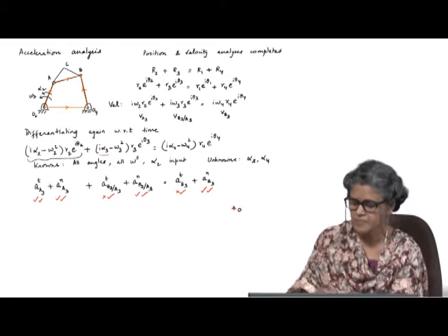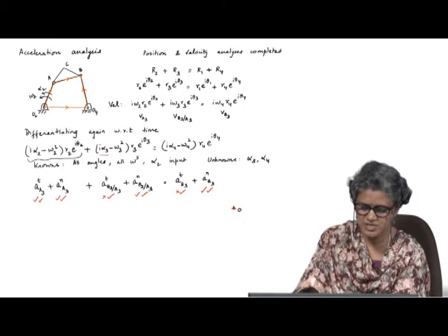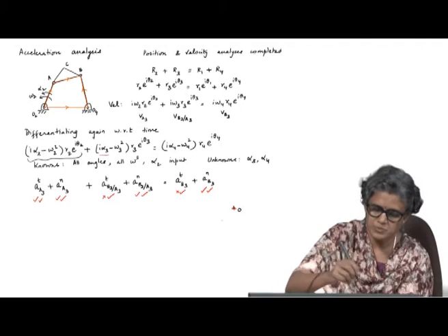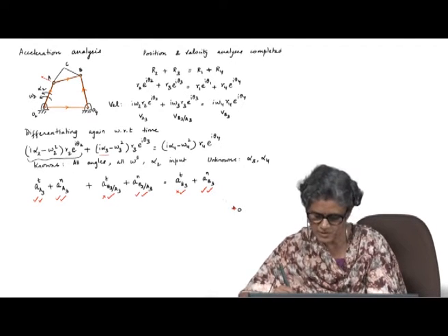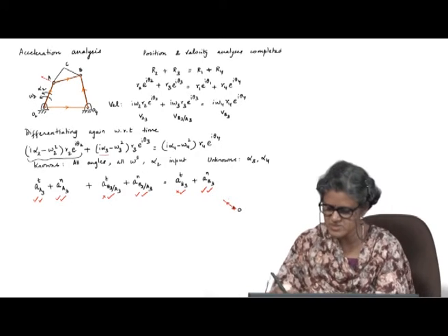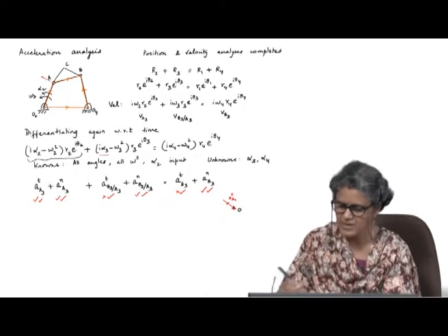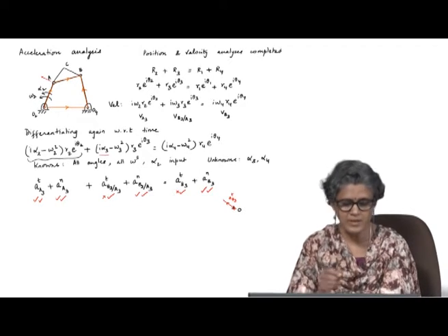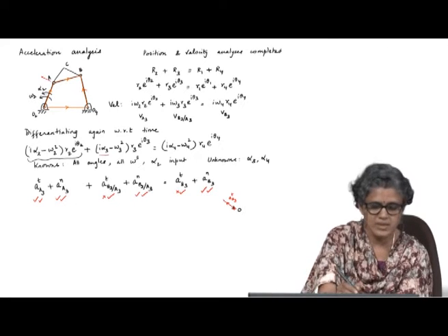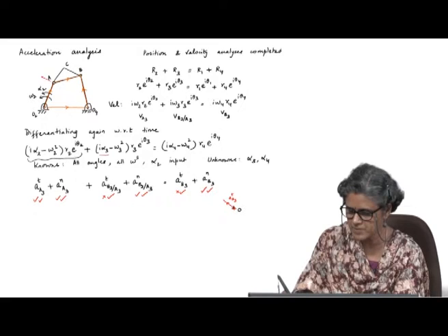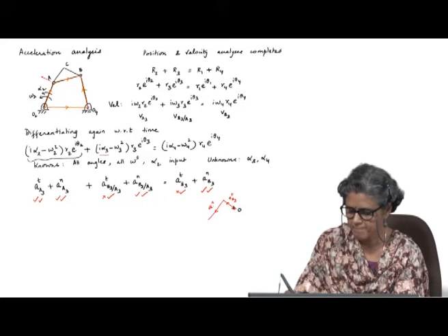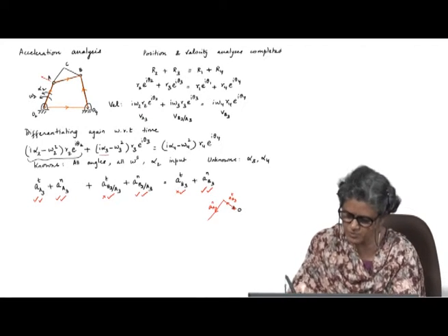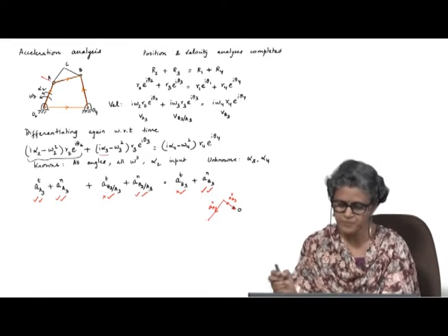So, if this is O, I know the tangential component of this, which would be like this, right, along that direction. So, this is A tangential A3, known. Okay. Normal component would be along from A to O2, that direction, that is also completely known. Okay. So, let us say that is this. So, I know this point here, completely known.